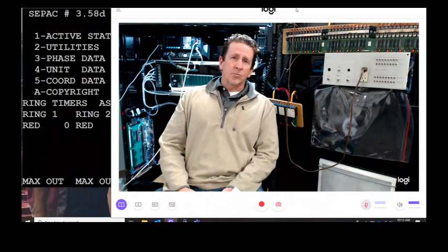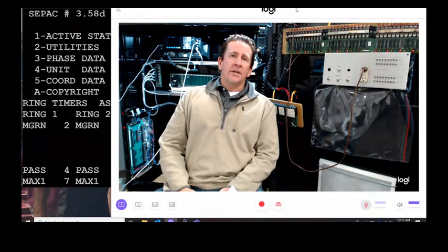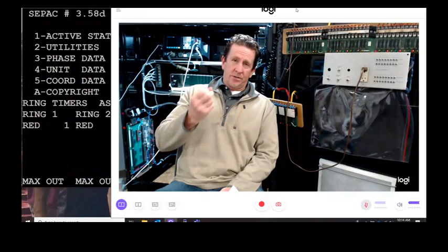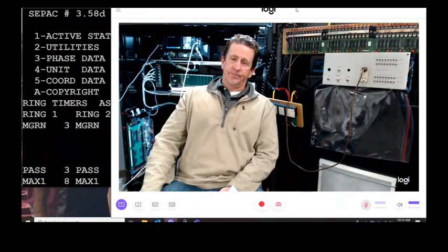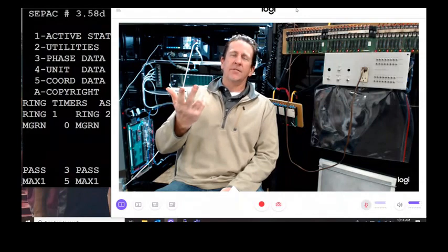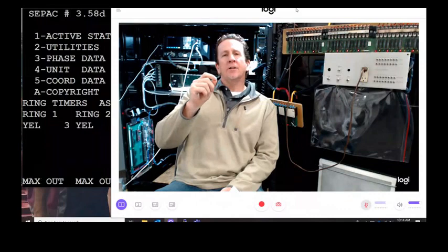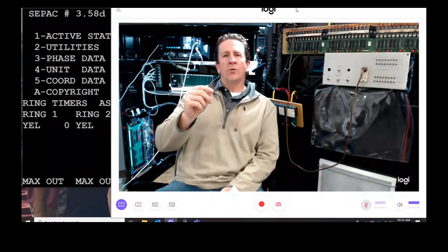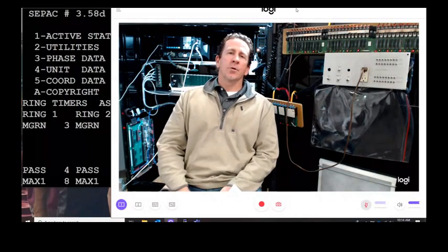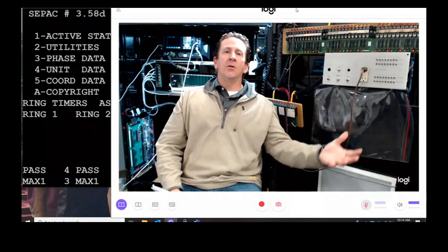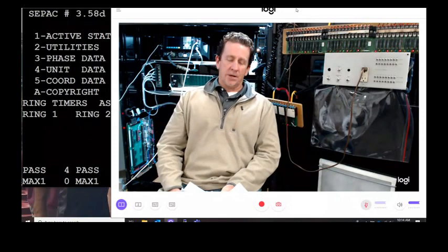And then the one last thing is when you open the cabinet, there's always a plethora of unpleasant smells in there, from rodents to gas fumes coming up out of the conduits. But the one we're keying on is that burnt electronic smell. I forget what it's called. But when an IC chip is burnt, it has that unique smell that we all know oh so well. That means that a component just got burnt up and it has to get replaced. So we want to check for those obvious smells and also the visual cues that we get.